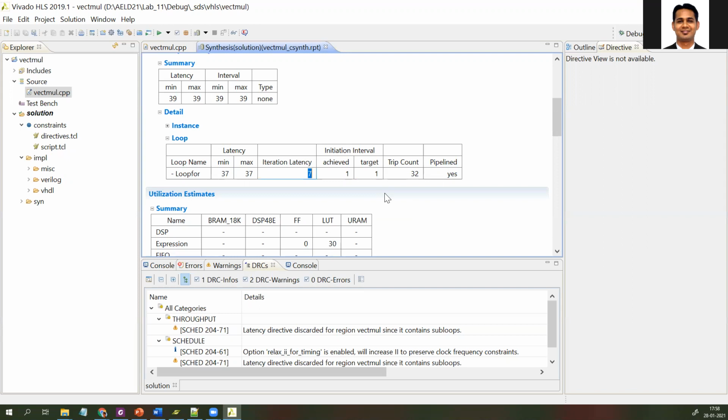Okay, so that means the time required for the execution of each iteration will be significantly less. Okay, so here I'm going to accept the 32 inputs in the first 32 clock cycles, because I'm going to have the initiation interval of 1, that means I'm going to accept the 32 inputs in 32 clock cycles. Now, if I accept A of 0 and B of 0 as the first input, the output will be available at the corresponding 6th clock cycle, because the last clock cycle is for the write operation.